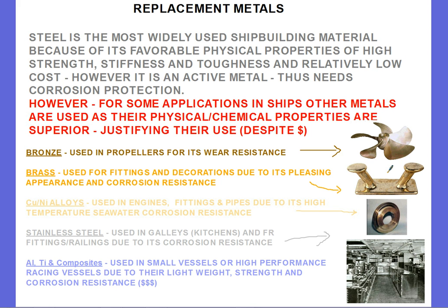Copper-nickel alloys are very good at withstanding corrosion, particularly in salt water and at high temperatures. So they're used in the engines, fittings and pipes, particularly because some ships have what's called seawater cooling. The engines are cooled with seawater, and to pump that seawater in and therefore pass around the engine at high temperature, you've got to use copper-nickel alloys.